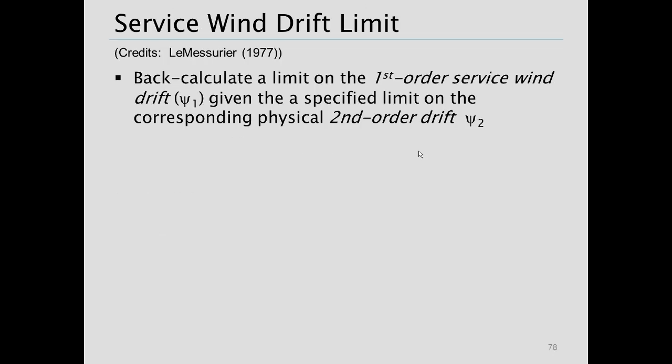All right, so this is the key slide here. The service wind drift limit, if we want to focus on something where we say, hey, I really want to focus on a damage limit under second order drift in our frames here. And so if I'm doing that, when we get our story stiffness design, there we're focused on first order service wind drift. And so we need to convert back from our actual limit on second order drift, and let's go with 1 in 400 as that limit.